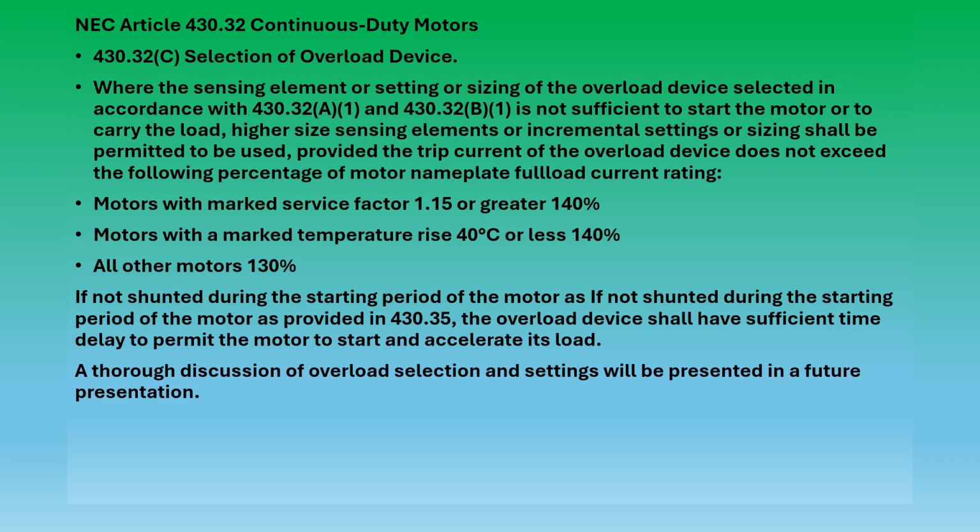But just remember, doing so, you're going to increase the heat of that motor. You're going to shorten its lifespan. And at the last location I worked, our electrical engineer would permit the motor overload to be increased to 140% for a short-term period.